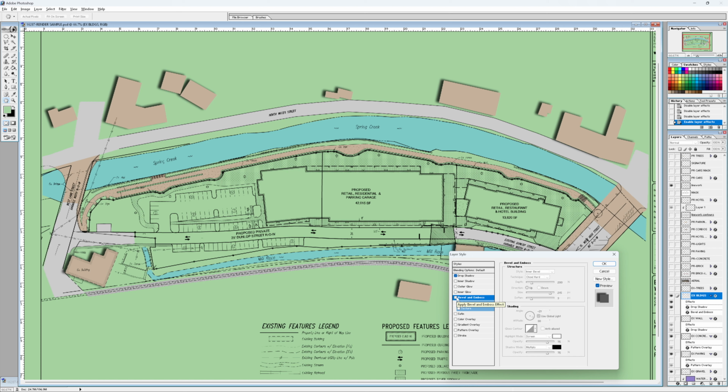So that's the key to, if your line work for your block is not clean, it will affect how your roof line looks. If you look up here, it tried to do a radial type of thing, so it's not exactly right, but again, we're just kind of roughing it in, getting the idea of what this unit may look like. I know this is a flat roof building, so it does not have a roof like that at all. So you could get really detailed and actually split apart different types of buildings depending on the roof structure so that you could add details later on.